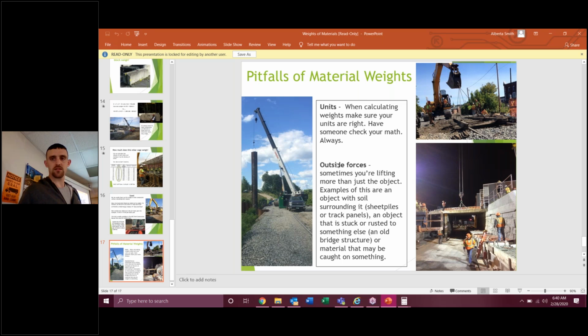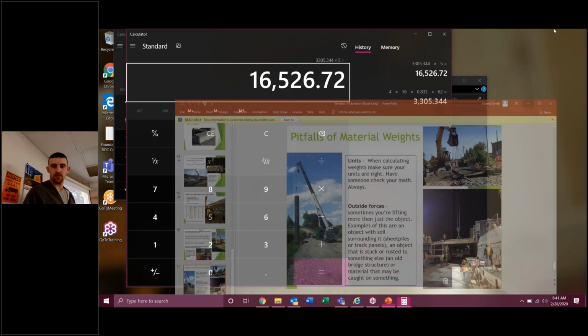That's all I got on outside forces. I also think wind on sheet piling, wind's a good one too. It can really push hard on the crane itself. Yep. Yeah, but we shut down operations in driving sheets in Middlebury yesterday just for that reason. So a huge area, you can get some big forces, dangerous with gusts especially.